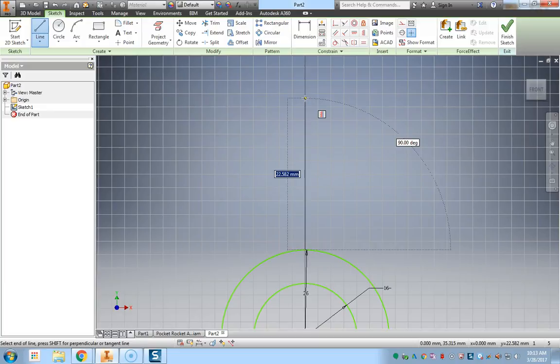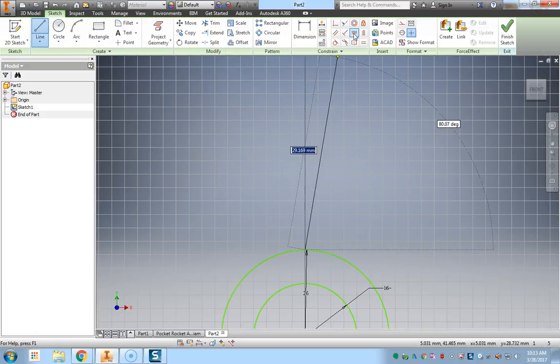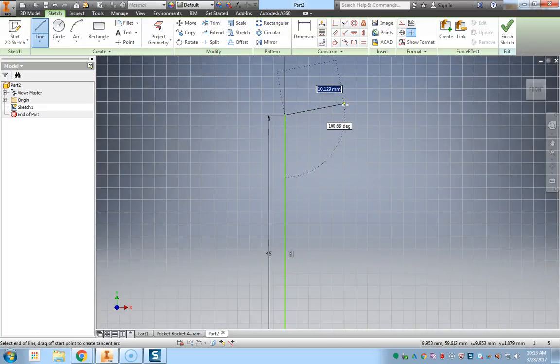And I know that it's straight by seeing the parallel sign that is indicated right there on the left, right of the mouse pointer. In this case, we're using the line tool, and that is found up here as well. That's the horizontal or vertical constraint. These are both parallel options to snap the lines to the parallel constraint. And I'm going to go up the 45 and hit enter. Okay. And then you notice that the next line segment is connecting off of the last endpoint, and I'm going to measure over 1.5.